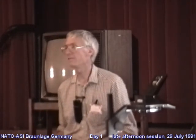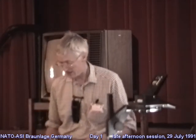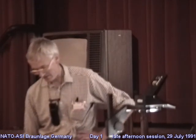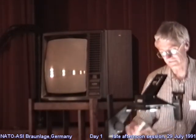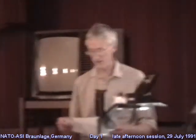A possible objection is that we don't detect any pull-off force in practice, normally, to separate the surfaces. This objection is not necessarily valid. I'll talk about that later, but just to anticipate a bit, the reason basically is that in order to achieve intimate contact between most types of surface in practice, a normal load is needed. All the same, this does apply to terms such as the strength of the adhesion, which is misleading if units of shear stress are used.